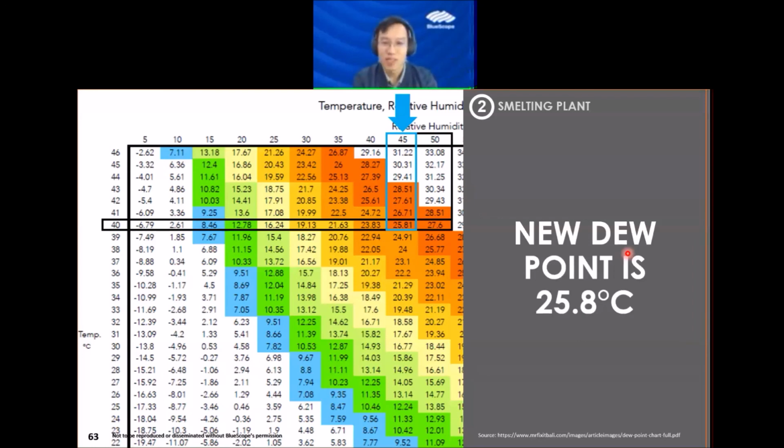So my answer to that was condensation. Because the internal temperature was so high and the air was so humid, condensation was happening underneath the roof. And because the water droplets are so heavy, they start dropping. So much water condensed onto the surface, then started dropping. So that caused the water droplets, and they thought it was actually leakages. So sometimes people are unaware of the effect of this type of industry. So this is why we have this kind of session.